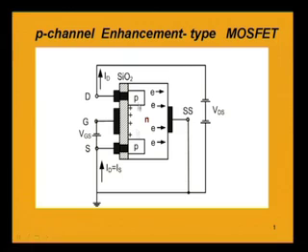So, this will be a channel having positive charge carriers, and when the number of positive charge carriers is enough to sustain the current, the drain current will flow, but the direction of the drain current will be as shown here, and it is equal to the source current. So, this is just the reverse of what we got in the N channel enhancement type MOSFET. So, the P channel enhancement type MOSFET will have the VI characteristic.